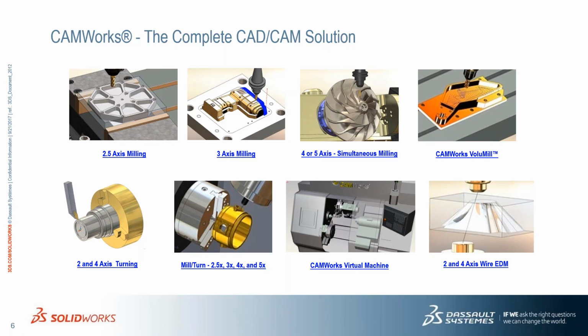The 2 and 4-axis turning modules for turning are offered by CAMWorks, and then the mill turn, everything covered there from 2.5 to 5. The CAMWorks virtual machine is the next step in simulating your toolpaths, simulating them inside a graphic representation of your machine itself. And again, this is another way that we can make sure that we're not running into any collisions with any accessories or parts of the machine as we're cutting the toolpaths. Then the wire EDM modules, also pictured there, are available with CAMWorks.